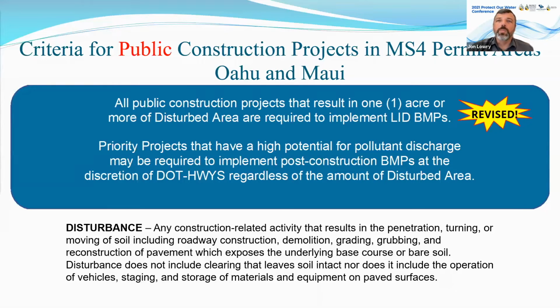And so all projects in these two areas that result in 1 acre or more of disturbed area are required to implement LID permanent BMPs. In the past, that threshold was 1 acre of new impervious surface. So we've now backed up to even if you're not adding a whole new acre of impervious, but you do disturb an acre of land, you are required to implement LID BMPs.